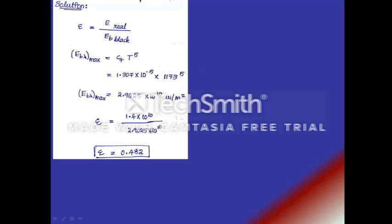Now let us take the ratio of these two values. We will get the value of emissivity. So emissivity is the maximum monochromatic emissive power of a real surface divided by the maximum monochromatic emissive power of the black body at the same temperature, and epsilon is found to be 0.482. Clear?